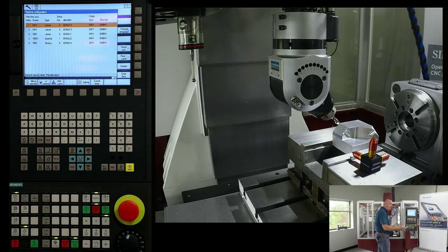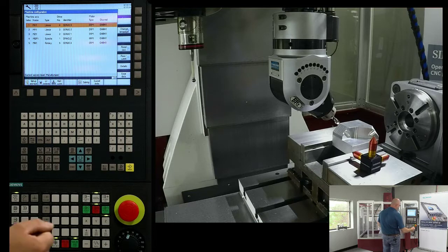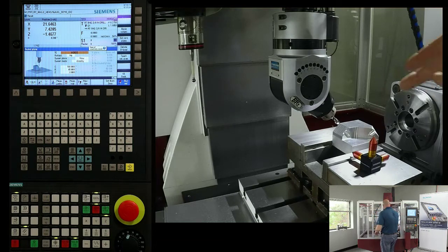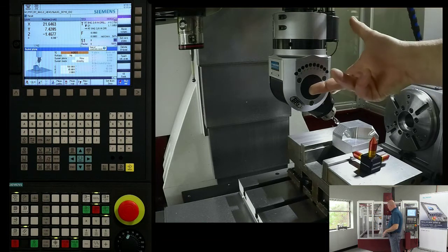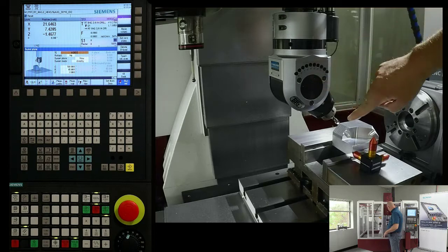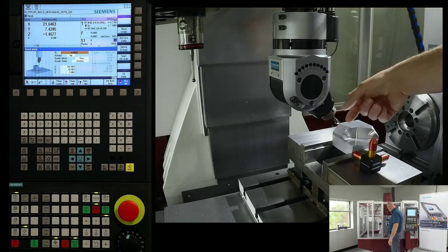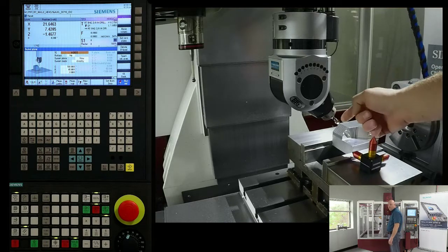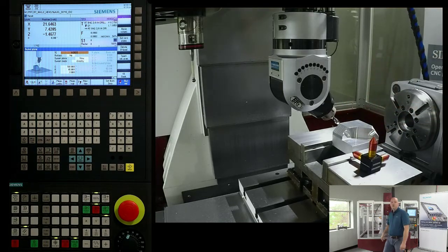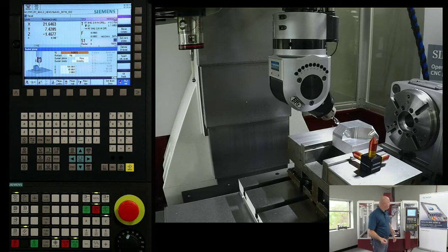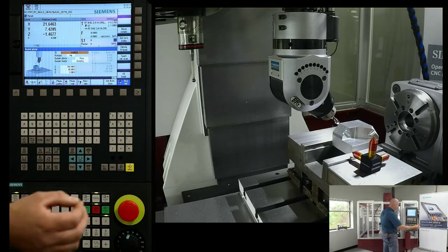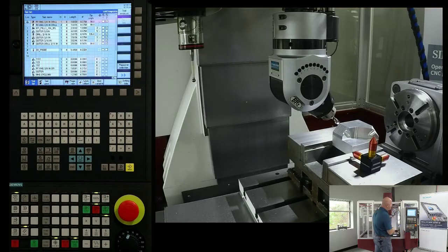So the next step is setting up my tool offsets. What I've done here, and we go back to the jog area and we can start to set it up, we have now a compensation value from our gauge line to center of rotation and a secondary value that comes out to the collet face. So now I have to compensate for this tool length, right? This projection out. And that's going to be my variable dimension. So that is part of the tool offset. So step one would be to create a tool offset for this tool. I do that by going into the offset table.